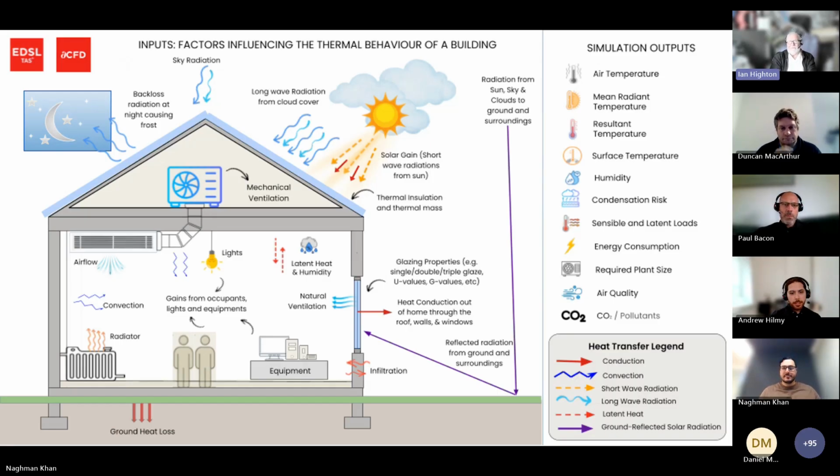But no, Bill, if you think about the way that the weather changes through a day, it's sort of sinusoidal. I mean, it can be -8, it could be -1, you can get massive fluctuations. And certainly, if you think about cloud cover and the way that the sunshine, solar gains, can change quite rapidly. We only get spot values for external temperature, and we get previous hour averages for things like solar gain, wind speed, wind direction. RH is a spot value as well. Sorry, by spot value, I mean that's the exact value at noon or 1 p.m. or 2 p.m.